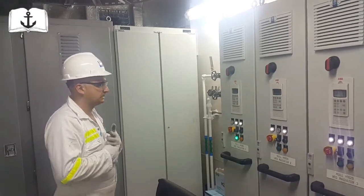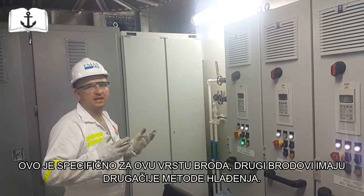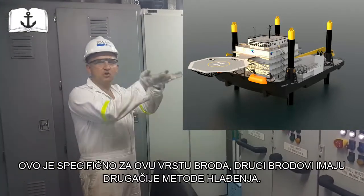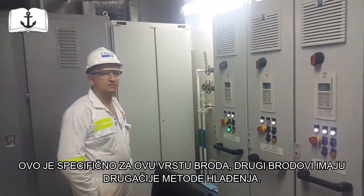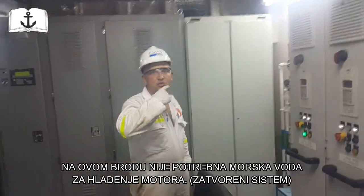So you don't need suction from the sea chest or anything? No, not here. This is designed like this because we are on a lift boat. Exactly. We should have said that in the beginning. The lift boat is the boat that can go up. Exactly. So it's not like a conventional vessel. We don't need seawater to cool down the engines. The only thing is we need a closed freshwater system, right? Yes, it's a closed system basically.